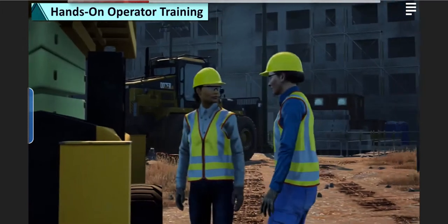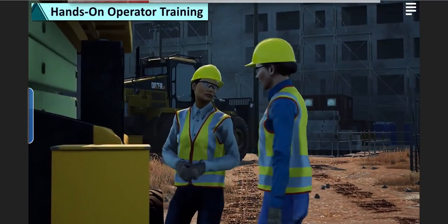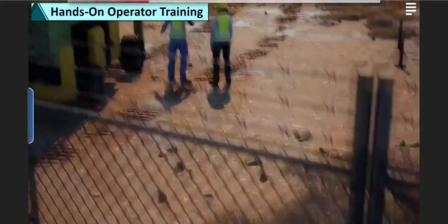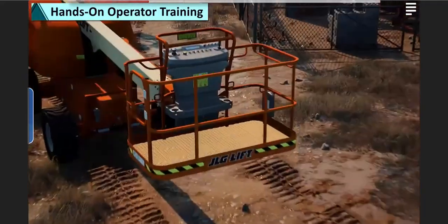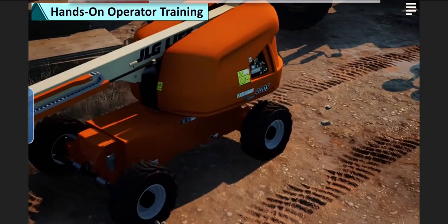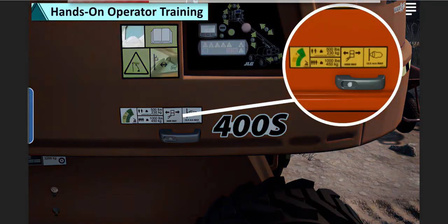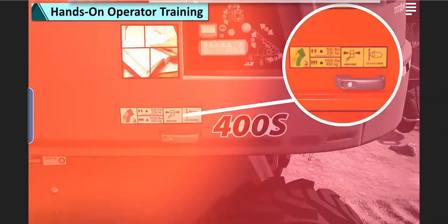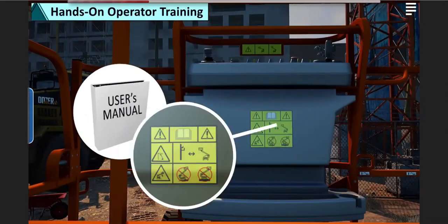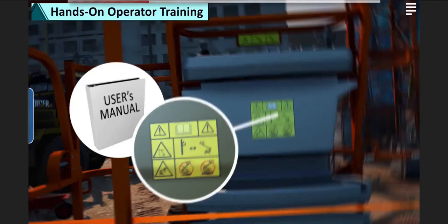The trainer must verify that the trainee knows how to perform pre-start and worksite inspections, carry out daily checks, and plan travel routes. The trainee must also be able to perform other pre-start procedures, including recognizing the purpose and use of placards and safety decals, identifying applicable safety rules, and confirming that the manual and other necessary paperwork is stored with the MEWP in its proper location.